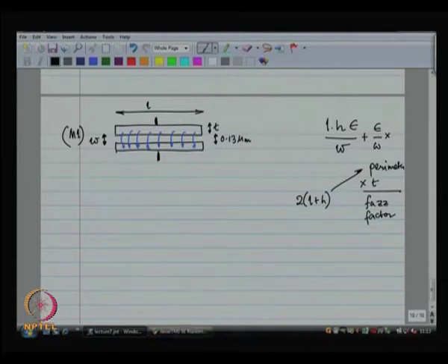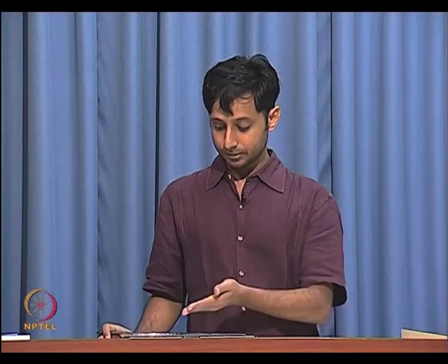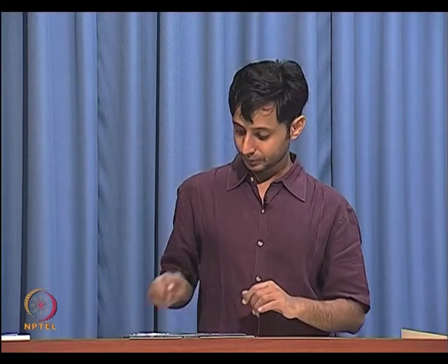Okay. So, you can basically put two wires parallel to each other, and that gives you a capacitance. You will surely get much better capacitance density than before, because now you can really squeeze down the gap between the two plates. Okay.